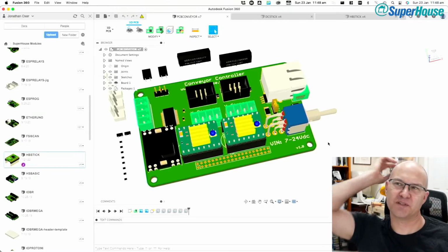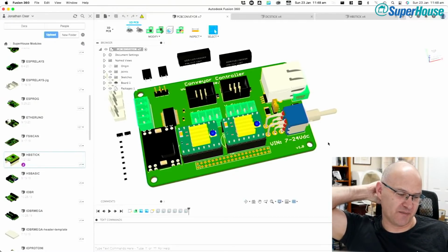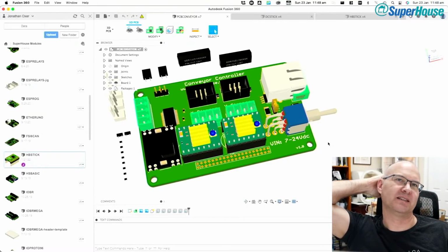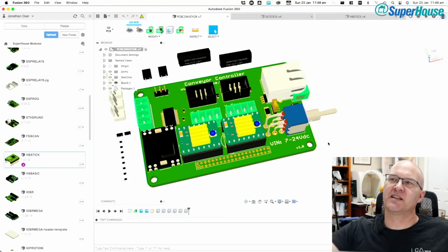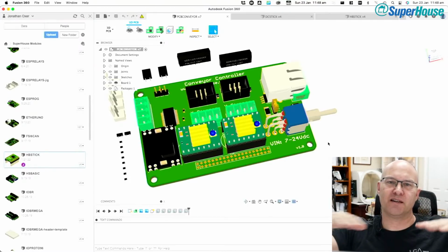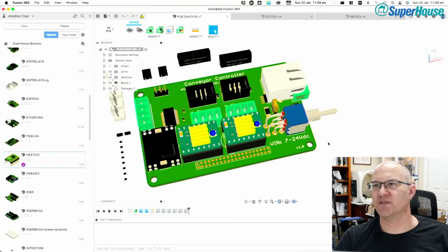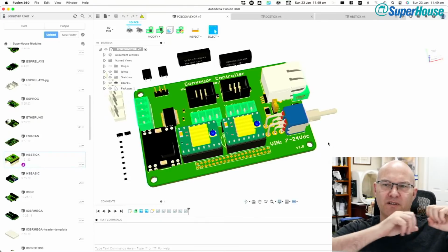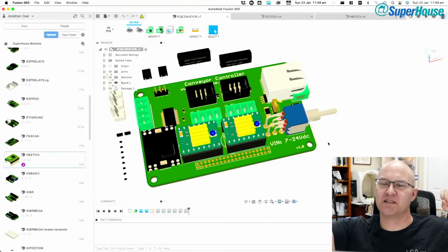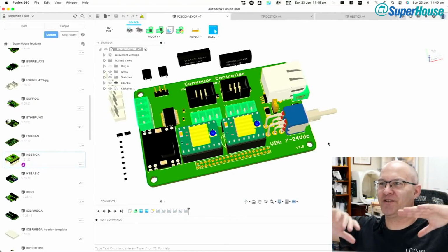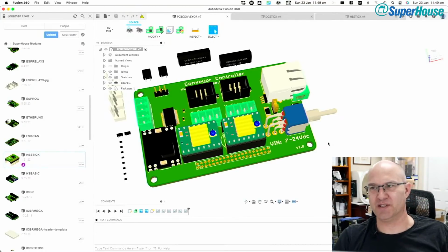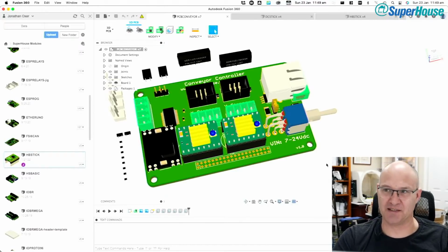So what I was thinking of was use cases where this is in a much more industrial environment. Like, imagine Steve was using this to set up a conveyor belt to run stuff into his plasma cutter. And so this is going to be having signals coming into it on wires that are meters and meters long, running past a plasma cutter, which is generating massive electrical noise and doing really, really bad things.